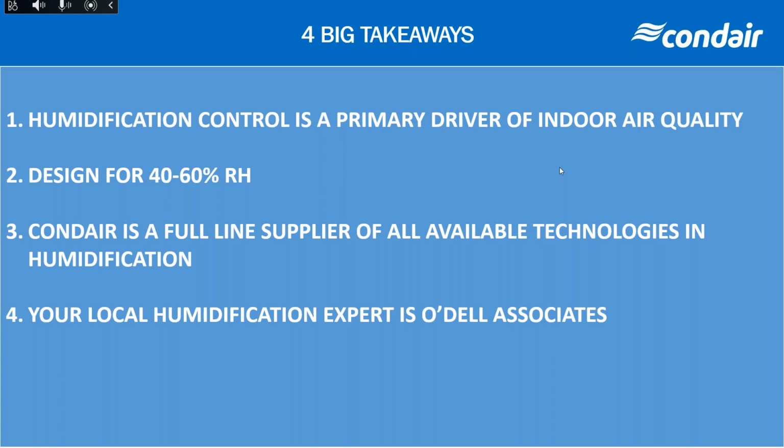pandemic has changed some of the regulations around outdoor air. For example, the European document, REHVA, I believe is the acronym, says that air should be primarily all outdoor. It should all be from the outdoor space and turn off recirculation. That's been modified, and ASHRAE does not support that because we realize there needs to be a balance between outdoor air and maintaining indoor humidity and temperatures without using an exorbitant amount of energy.